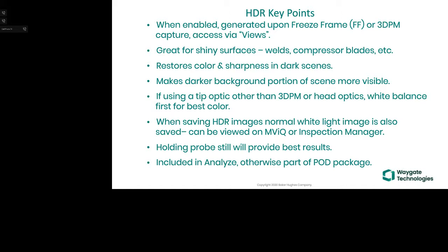And it's really handy when you have reflective surfaces and when you're looking at areas that you want to measure, especially with stereo measurement, you can adjust the high dynamic ranging to get better pixel pattern differentiation, which is critically important with stereo and 3D stereo. So it's that tool that's allowing you to change the brightness and darkness on the scene to get better imaging and also allow you to have better and more precise measurements.